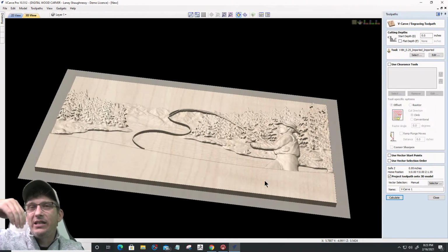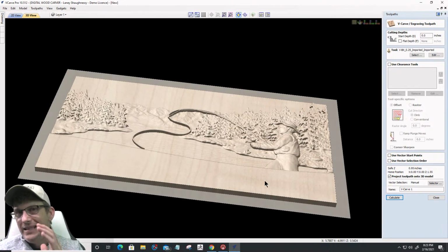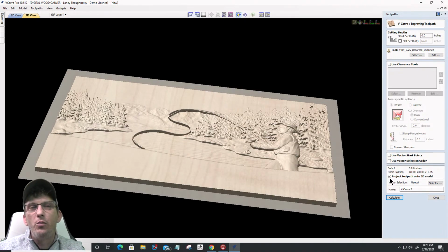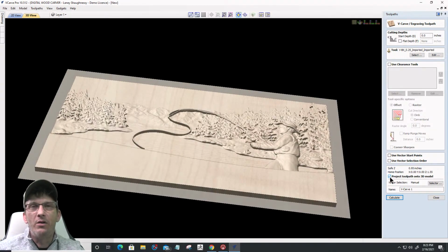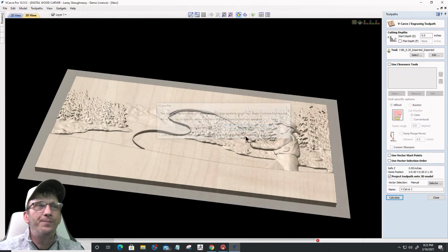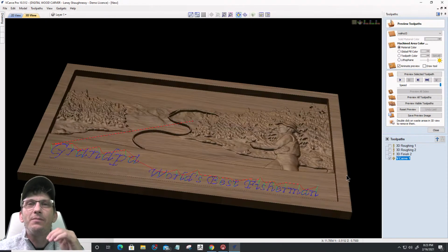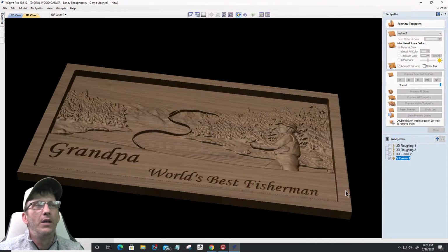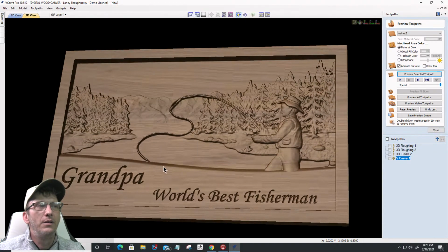Can I just add that cut depth, like that 1/4 of an inch, and start from there? Yes, technically you could, but it would be best if you projected that whole toolpath down onto the 3D model and started from 0 from there. So when I project that toolpath, it's now bringing this surface plane, this surface that my model is at, that's my 0. So now when I carve, it's carving into that design, right?